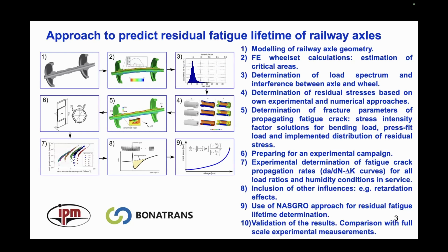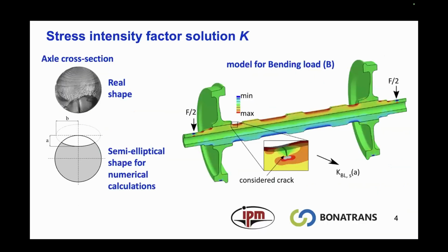Then we prepare a finite element model with cracks, and we simulate crack propagation in the axle. It is important to know the material characteristics for crack propagation well. We consider some retardation effect, and for the final calculation of the lifetime of the axle, we usually use the NASGRO approach or some modification of this approach.